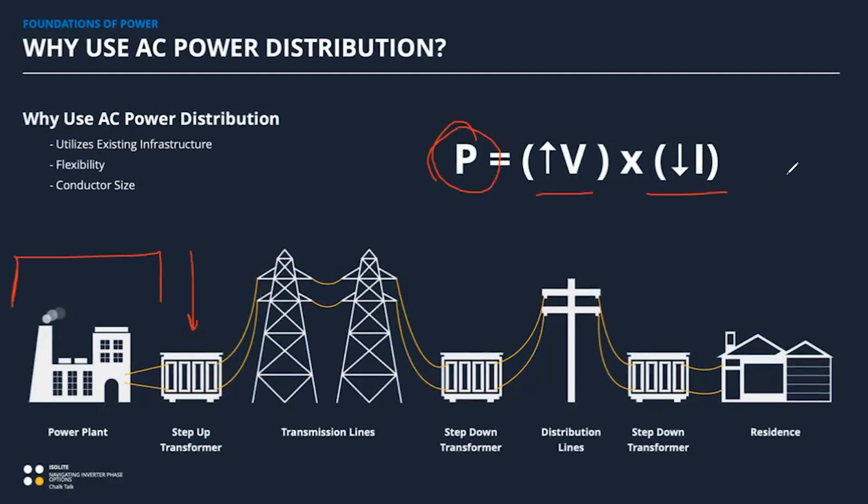More current, generally speaking, needs larger wire. So, if you've wired your house, you might know that a 15 amp circuit only needs 14 gauge cable, whereas a 20 amp circuit needs a 12 gauge piece of wire in there. And that actually goes all the way up.